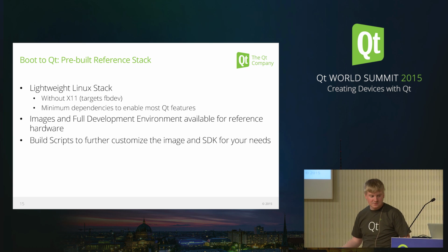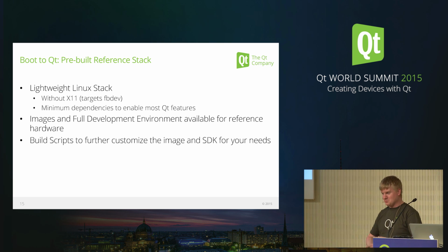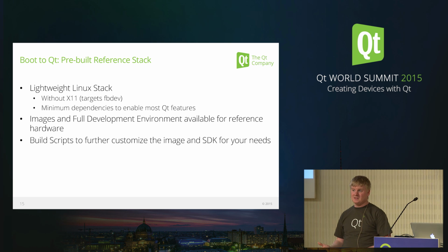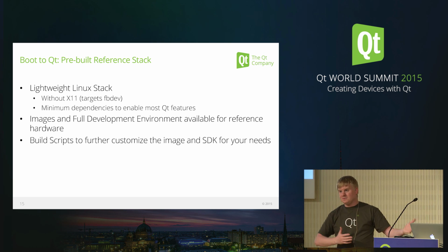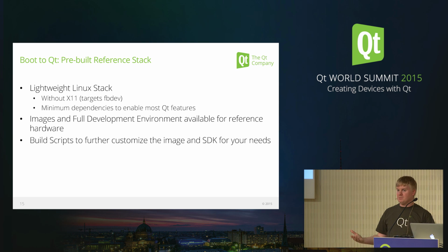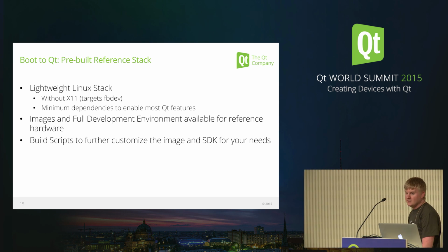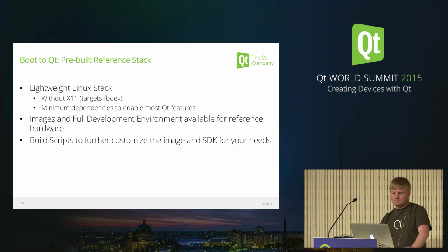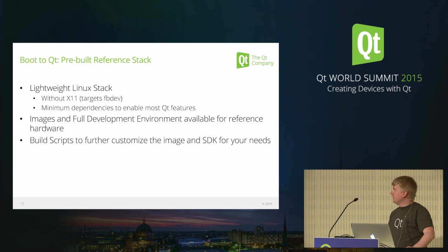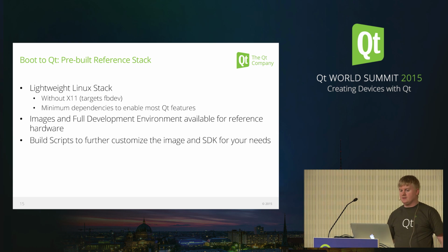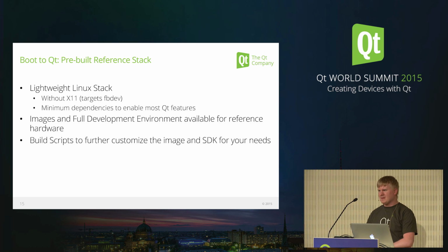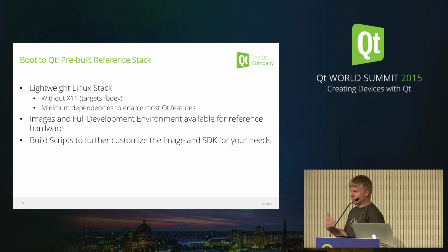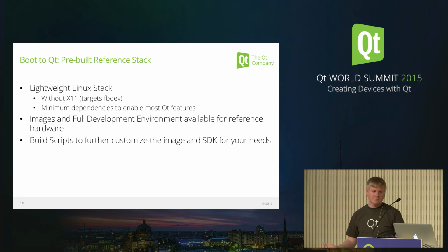It boots up to a launcher, just to show you what the device is capable of. And then we also give you the SDK to develop software for that device. So the tool chains and the sysroot that you actually need. And then have Qt Creator configured to already deploy to those devices. So, a little bit about this Boot to Qt reference stack. It's a lightweight Linux stack, so basically the bare minimum that you need to build Qt with all of the features enabled.